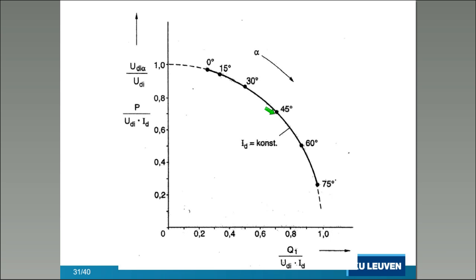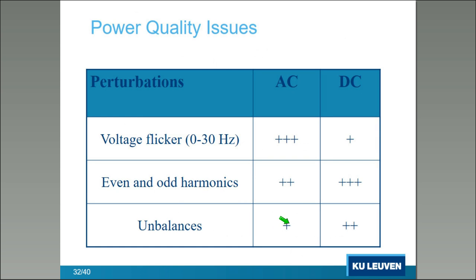But that means that the unavoidable variation in active power gives no magnification of variation in reactive power. So with the direct current arc furnace, we have less or not that nasty flicker problem.